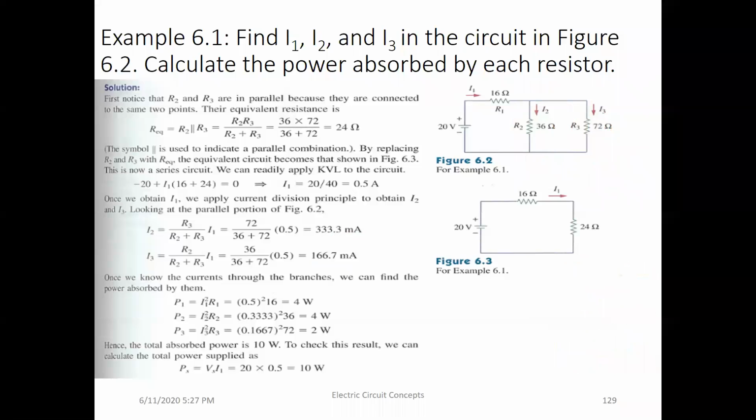Okay, so if I determine V1, V2 and V3, then I have the option to use one of the formulas. Remember, this is very important. If I need to find the power P1, P2, P3: P1 is V1 times I1, because I call this V1, or I could use I1 squared times R1, or V1 squared over R1, since I know V1.